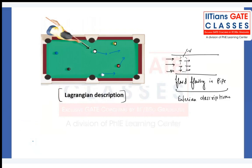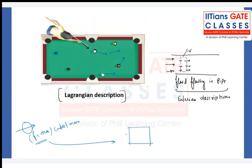Which equation will connect the gap between the Lagrangian description and the Eulerian description, or the control mass system and the control volume system? Because when you apply Newton's second law, F equals ma, for a ball, this is valid only for a control mass system, for a single particle. But you are applying it for a fluid particle also. This net force, as we have seen in the derivation of Navier-Stokes, we have applied even without taking permission from the Lagrangian.